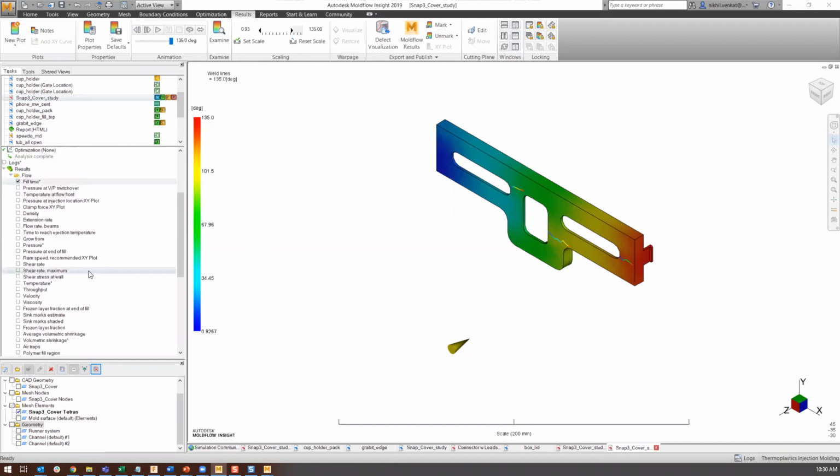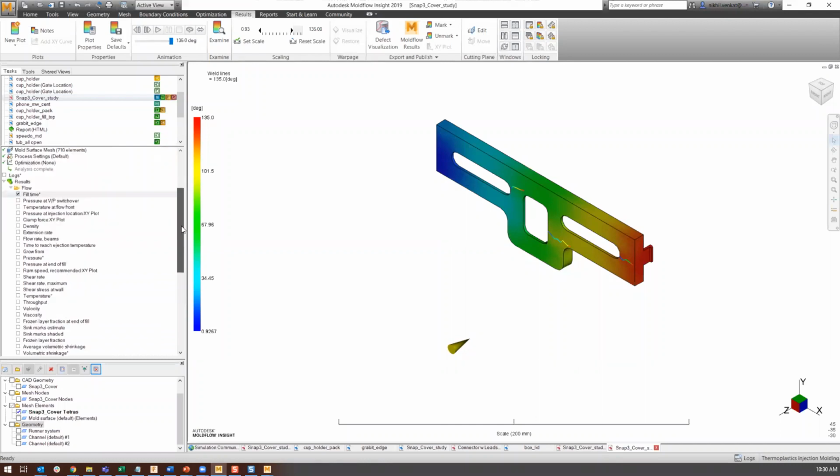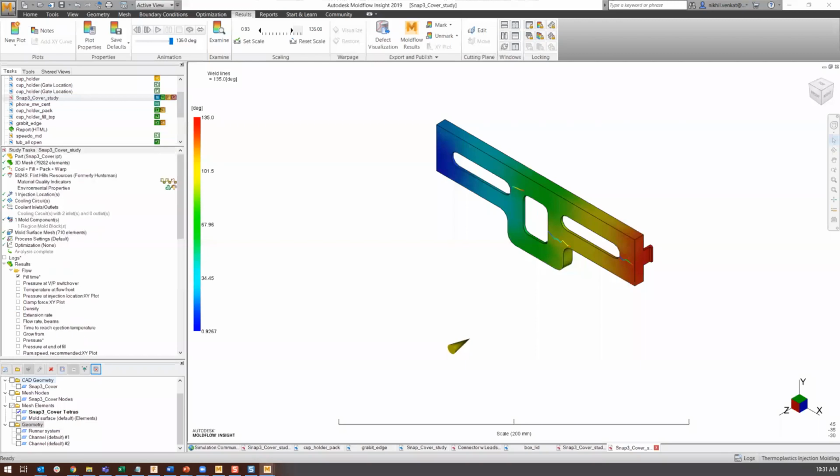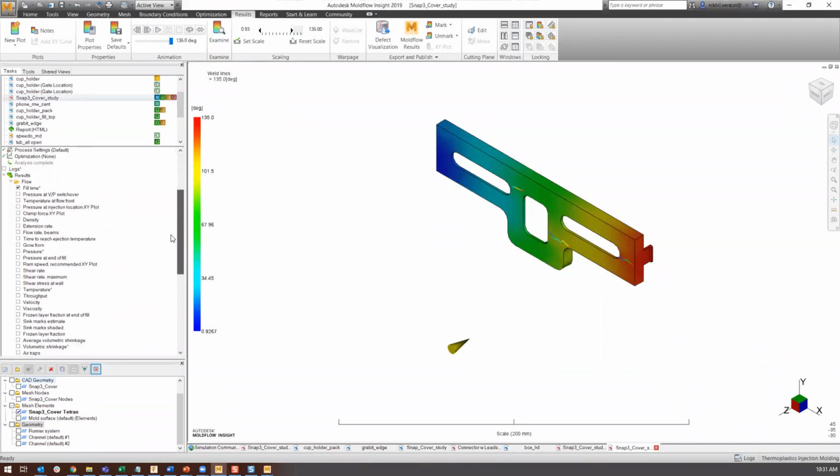Yeah, the idea here is, again, to understand the propagation of these weld lines and how it's related to the actual filling of the part. If you see there's no issue with the filling of the part, but you see there's weld lines all over the place, then that's likely because of something else. Yeah, no two weld lines are created equal. Just how the flow front comes together, maybe backfills towards the interruption in flow. These are dynamics that can make air entrapment or more difficult to get a good weld. Does it butt and stay stationary, or does it move downstream? These are all dynamics that are great to visualize by overlaying different results. Yep, absolutely.